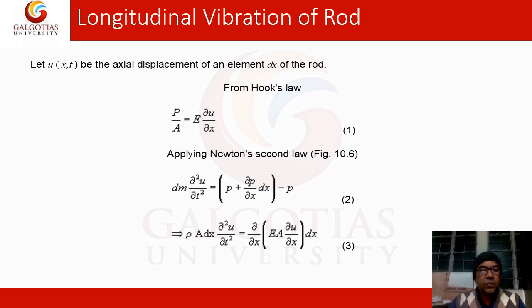In the previous rod, we have to derive the equations of the wave introduced by the force applied in the longitudinal direction. From Hooke's law we can write P by A equal to E ∂u/∂x, where E is the Young's modulus, and applying Newton's second law of motion, we can write